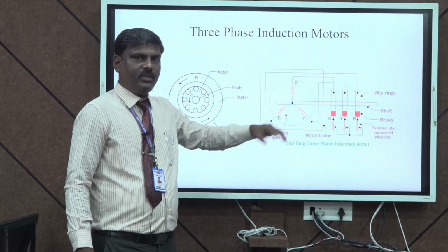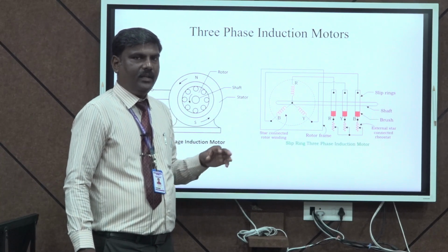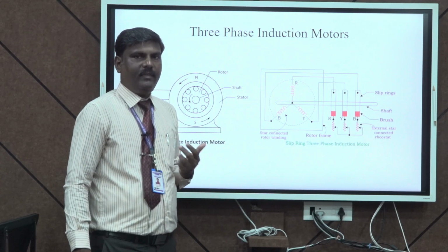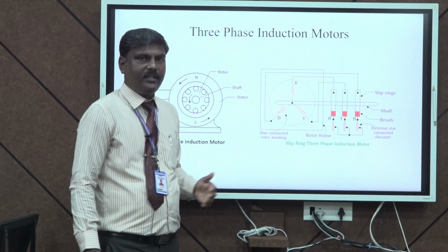By varying the rheostat, we can vary the starting torque of the slip ring induction motor. Through this slip ring induction motor, we can also recover slip power. So that is the biggest advantage of the slip ring induction motor.